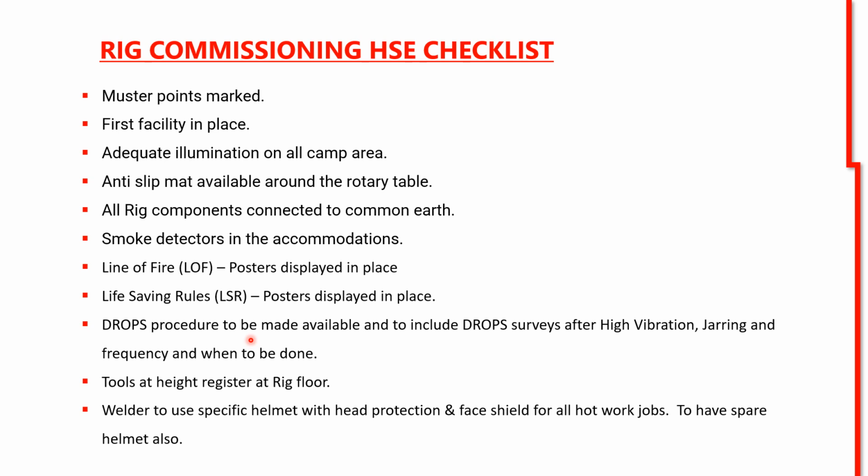Drops procedures to be made available and include drop surveys after high vibration, jarring, and there are some frequencies. Okay, weekly, monthly, and when to be done as per the client advice. Tools at height registered at the rig floor. Welder to use specific helmet with head protection and face shield for all hot work jobs. To have a spare helmet also.